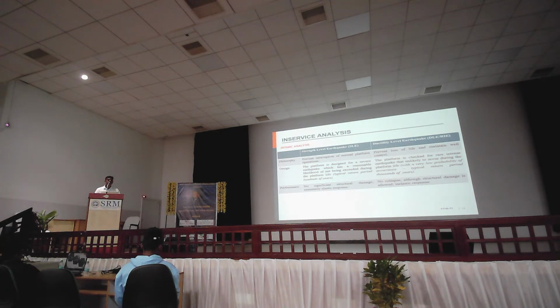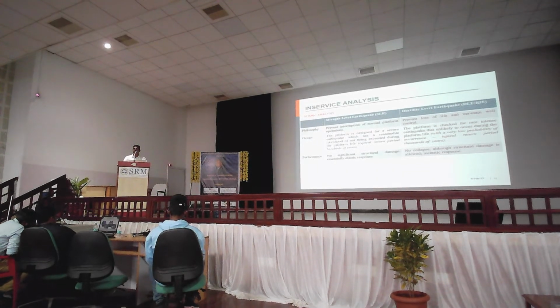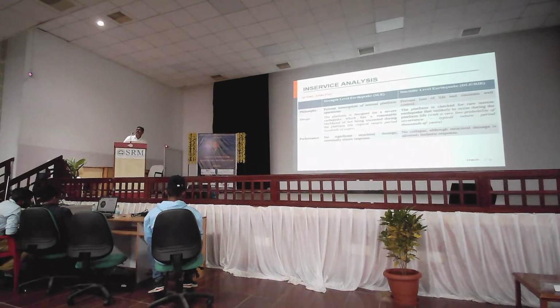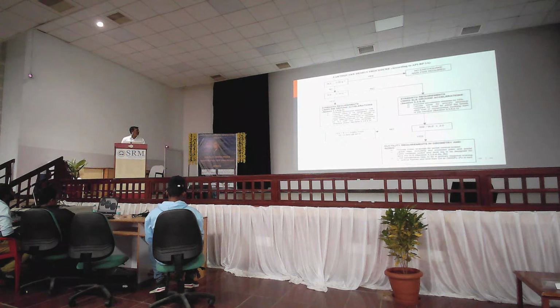We are designing our structure for close to a 100-year event, and for that case the structure should be elastic. Elastic in the sense the stress should not go into the plastic region. But for the rare event, we can allow our structure to fail, but it should not collapse immediately. People should escape. So these are the guidelines given in the API code.